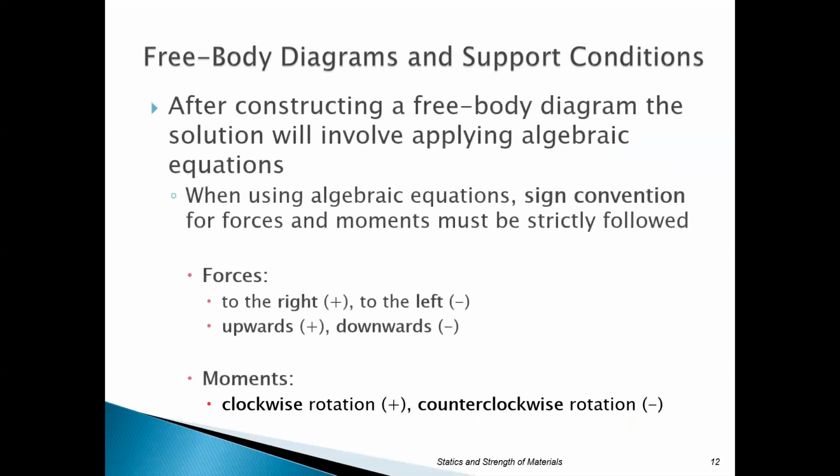Okay, also remember, sign convention is really, really important as we get into this. Forces can be considered any direction you want, but most people consider a force to the right positive and a force to the left negative. Kind of works with the same convention that we use for the rectangular coordinate system. And upwards is positive and downwards is negative. But truly, you can do this any way you want as long as you're consistent throughout the problem.